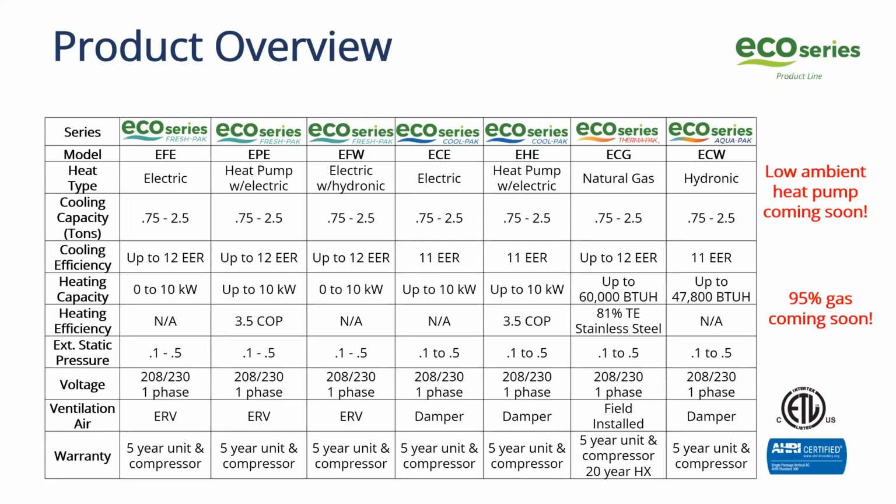This one is available in 3/4 through 2.5, where the other unit was 1 to 2.5. So we go down to that 9,000 BTU of cooling, get more down into the range of the PTAC and the smaller units there. The unit size is pretty comparable to the 1 or 1.5 tons, so there's not a lot of space savings for the unit.